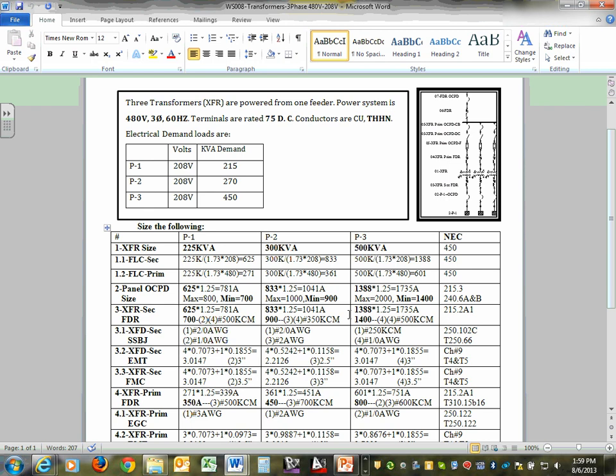If you have a manufacturing floor, guys, and you have the choice, ask for 480 equipment. Your process equipment that you're going to buy from China or anywhere else, ask for it to be rated for 480 if you have your choice. So what if all the equipment are rated for 208? Now I need to step down the voltage and feed these chunks of loads concentrated in one manufacturing floor area with a panel, or a bus duct. We use a bus duct with these. That's where you encounter something like this.